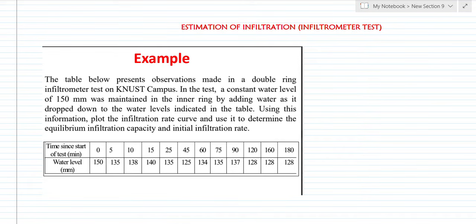When it rains and the soil is already saturated, the rate of infiltration will be low. When it rains and the soil is dry, the rate of infiltration will be high. If it rains over a highly compacted soil, the infiltration rate will be low because the water has to pass through tiny pores. If the soils are compacted, it means that the pore spaces are reduced.